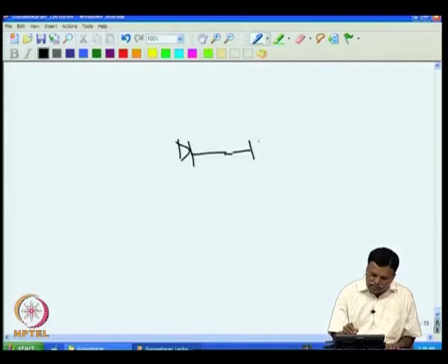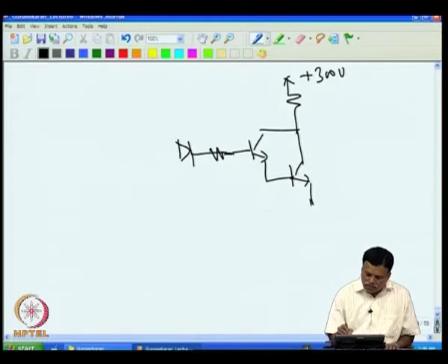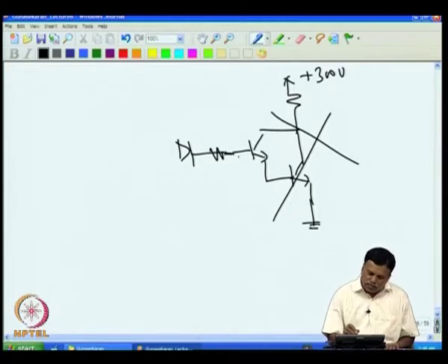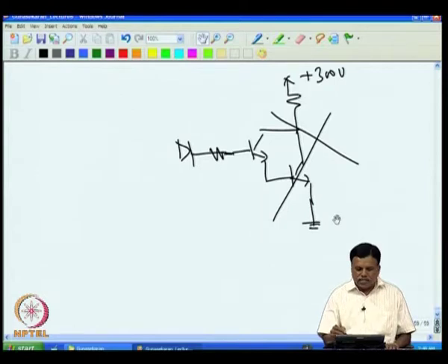Like what we have done in the on off controller, I can put this drive and I put this. So, for example, here plus 300 volt I put, and then put this and then put this. This will not work, because what will happen is that if this voltage increases linearly, the voltage across this will not increase linearly. This is a major problem, because we want that if the error voltage increases, the voltage across this heater should increase linearly. That will not happen in this circuit.